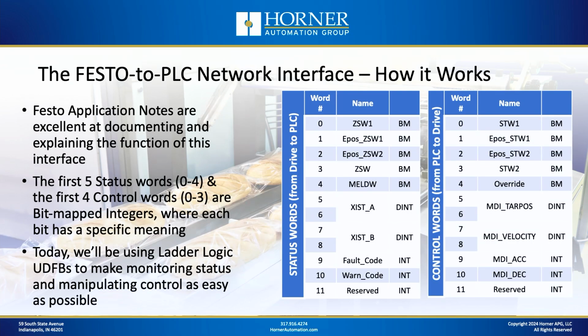Okay, now taking a little closer look at these status words and control words and how those are designed by the Festo folks. One thing to note is Festo has several different application notes which go through this in detail, and I would highly recommend you check out their great application information. Basically, the way they've designed this interface is that the word exchange is the same for both Modbus TCP as well as Ethernet IP. So really the documentation applies to both. So again, lots of great application notes available on the Festo website.